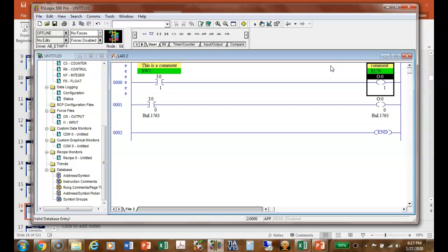Now, once I've assigned a symbol, if we need to reuse it, we can use the symbol instead of the name. So every one of our instructions, we're going to assign symbols. And that'll just get you ready for newer PLC applications that require tags. So tags, if you read about tags in your newer PLC language, those are the same as what these guys call symbols. Everybody okay? Does this make sense?